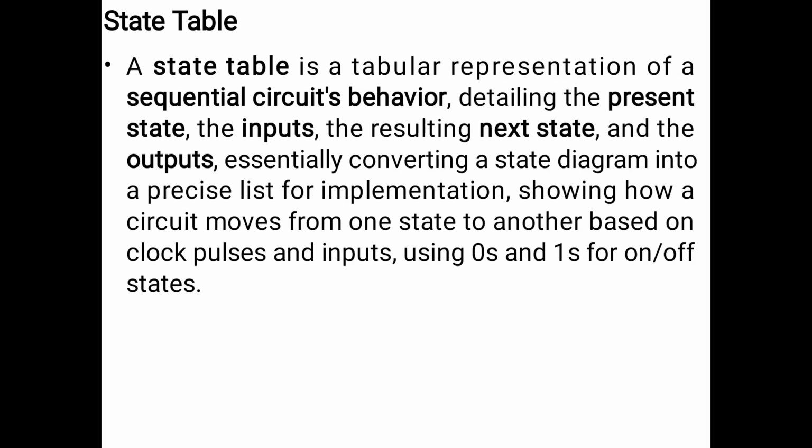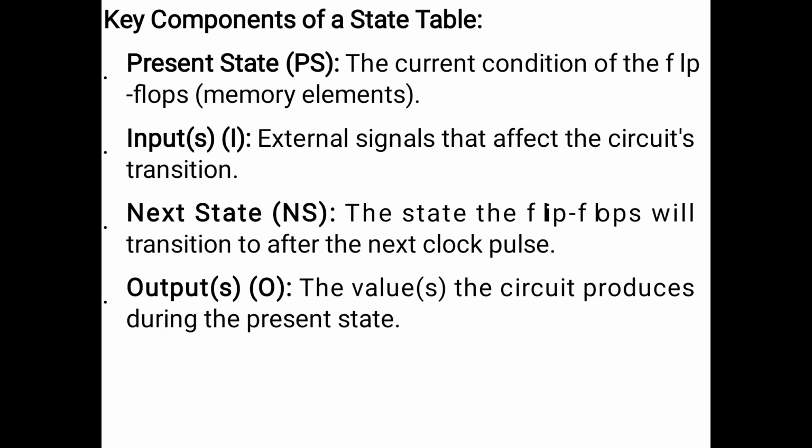A state table is a tabular representation of a sequential circuit's behavior which details the present state, the input as well as the resulting next state and the outputs, essentially converting a state diagram into a precise list for implementation, thereby showing how a circuit moves from one state to another based on the applied inputs as well as the clock pulses, using zeros and ones for on-off states.